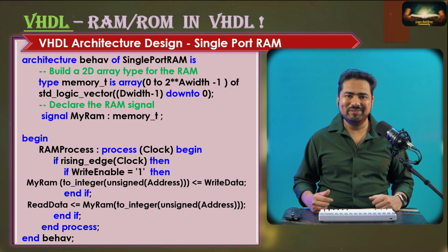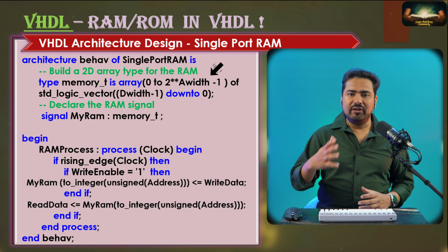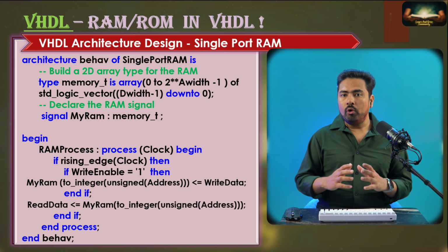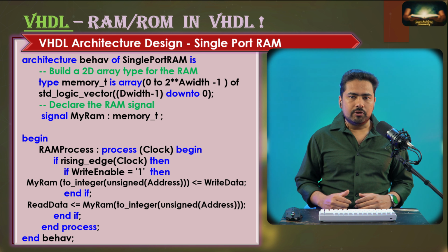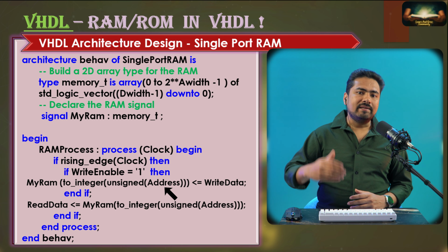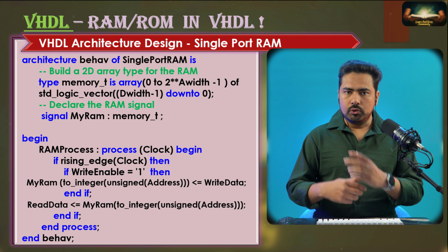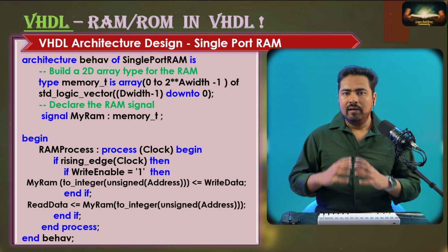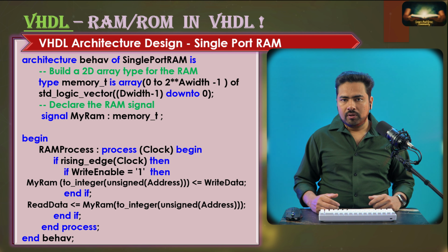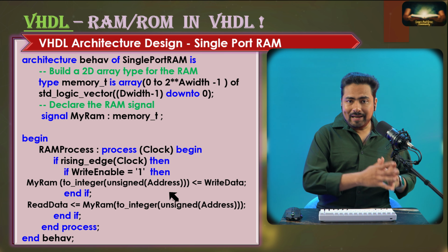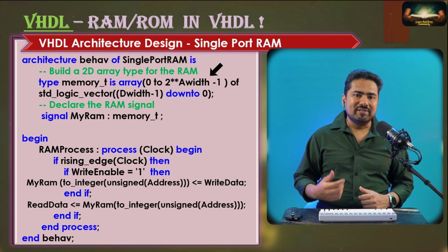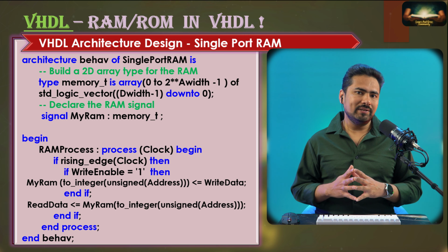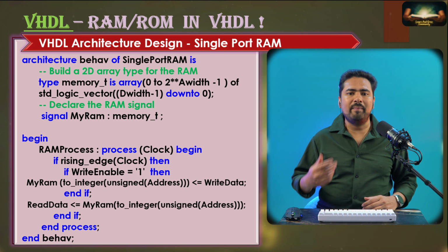Now what is this? Well, our address has a range like 0 to 255 or 0 to 1023, etc., depending on the A_WIDTH parameter, which means it is an integer. And our input address is a std_logic_vector signal. So we need type conversion here, like we discussed in the previous sessions. This statement will convert that std_logic_vector signal into an integer number, which will be our address. I hope this is clear because this will be used a couple of times in our memory section.